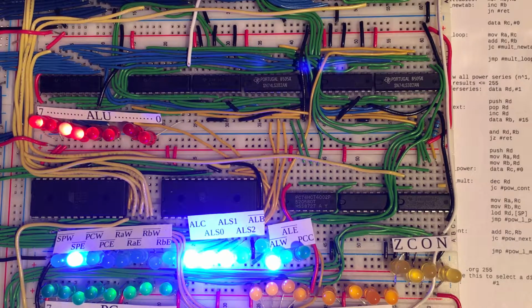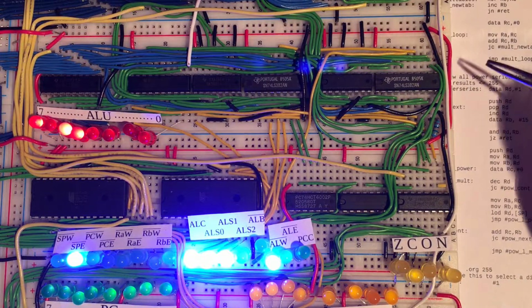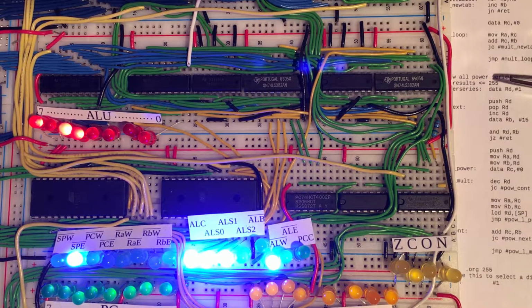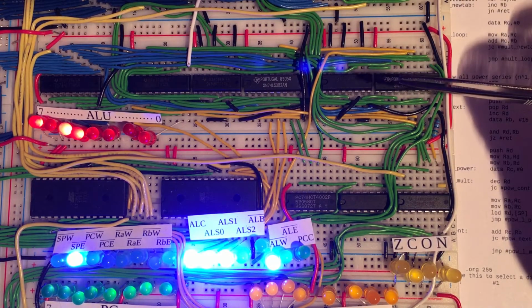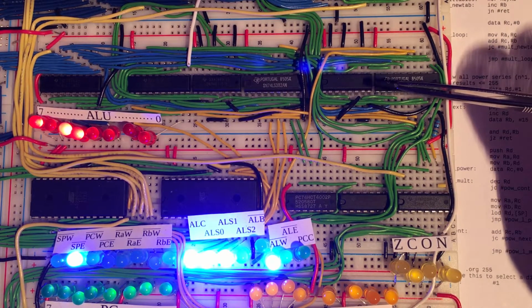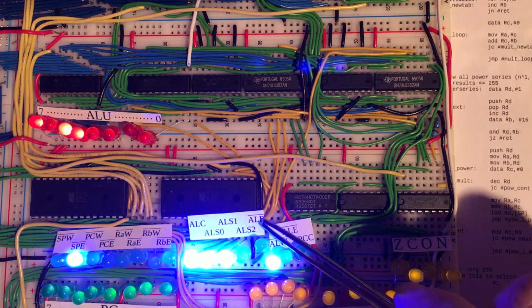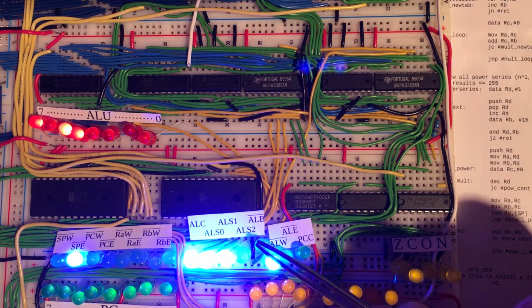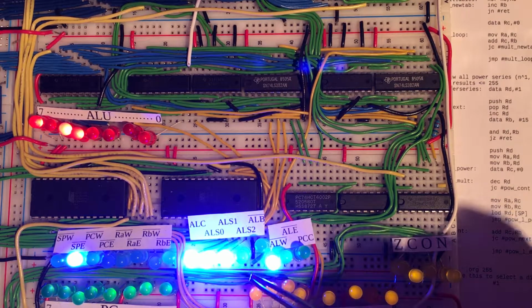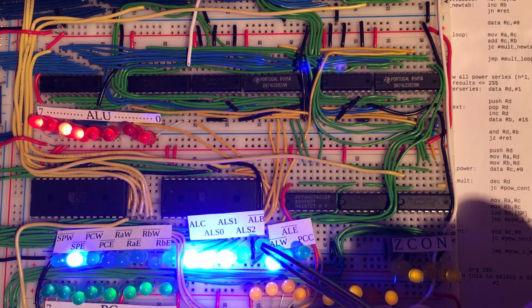Now finally, remember that the second operand is either the B register or a hard-coded value, which so far we've called 1 or -1. And so we have a final signal from the control logic here, which is this ALU B signal. And so that tells the ALU whether it should use the B register or its hard-coded value to perform the calculation.